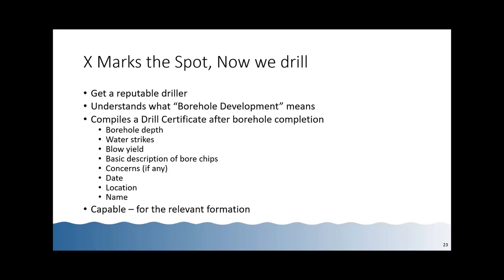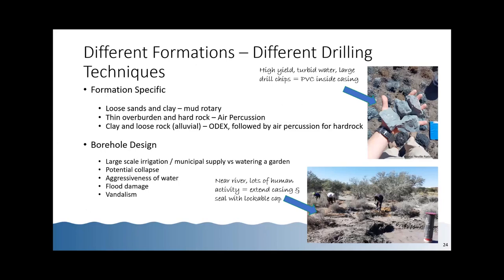In South Africa, we've got different geologies. We've got a lot of different professors coming to this country to study here because we've got this wide variety of geologies. That means that your driller has to be capable for those different geologies. For example, you are on the west coast in that unconfined aquifer that Corné talked about, you've got to use the mud rotary method. That's specific for loose sands and clay. And in this method, as the driller goes down, he uses a fluid to keep that loose stuff from collapsing into your borehole.